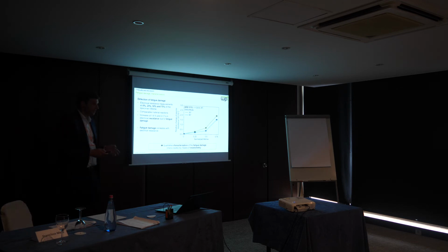So I investigated the specimens you just saw with fatigue tests, and measured the resistance with the same setup at 25%, 50% and 75% of lifetime, and plotted the results in this graph, the relative change of electric resistance, to compare those results. You see there's a pretty comparable material reaction, but the 30 degree with less damage shows a little bit more of an electrical increase.